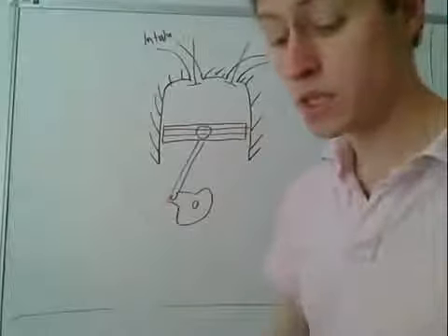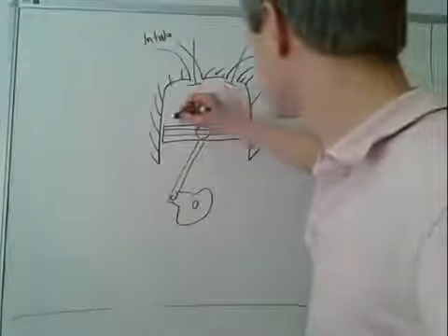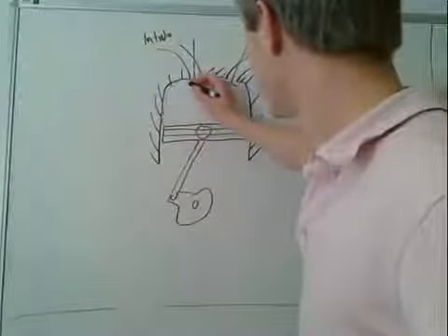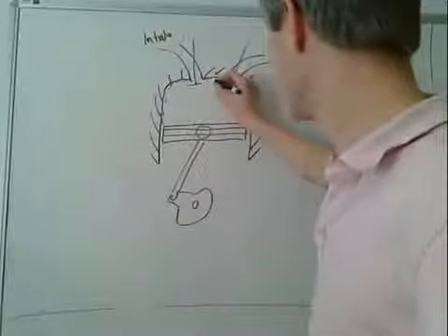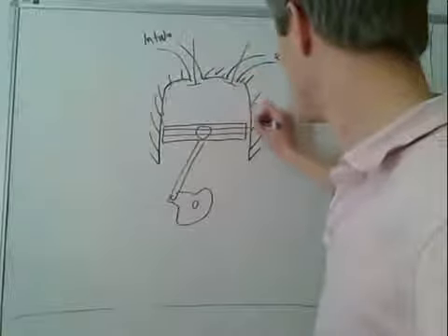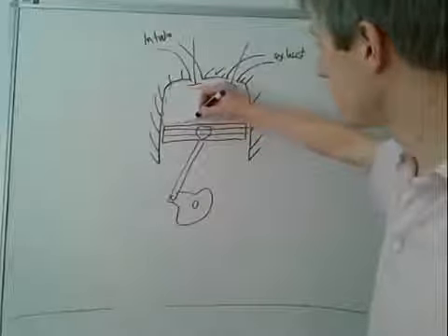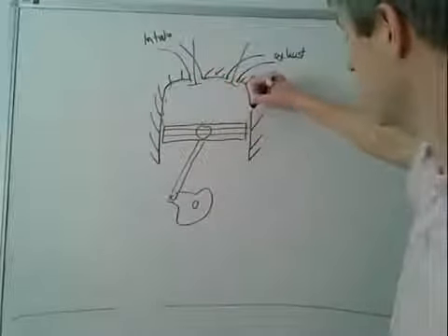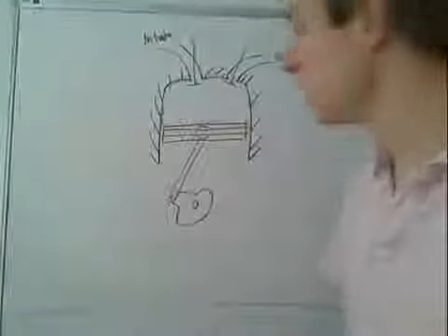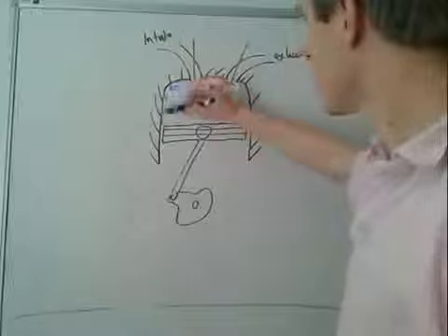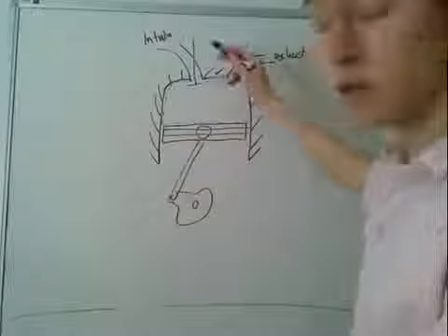So what I suggest might be useful to do is to have a system that just contains gas, and you could do that by having the system boundary go along the inside of the metal here to cut across the valve ports here. And now the piston is moving, but we could have a moving control system or control surface. So we'll just draw it along the surface of the piston metal. So now we have an only gas system. When the valves are open, it's an open system.